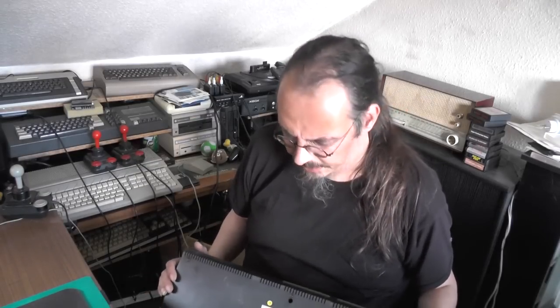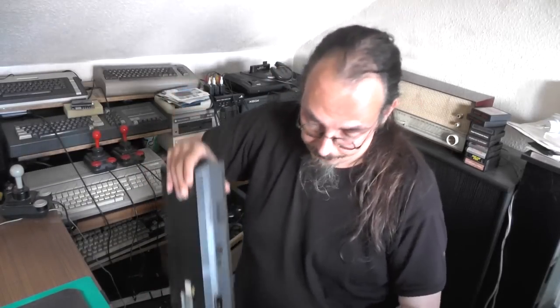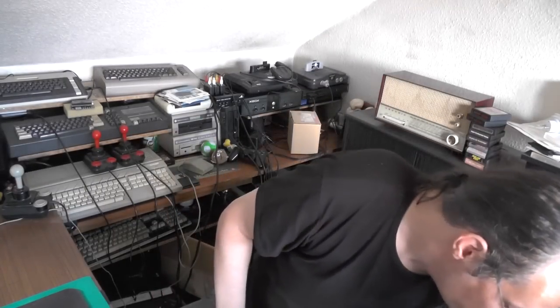It has no hardware scrolling. Well, there is sort of hardware scrolling, but it's not documented by anyone and was rarely used in any games. No sprites, and the frame buffer is 16K if I remember correctly. So the 4 MHz Z80 has to manipulate a lot of memory to move anything on the screen. So most of the games are pretty slow.